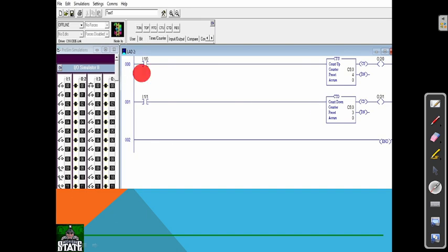If it is a sensor or an on/off switch, if I press this button over here 4 times, because here I denoted a count of 4, turning it on and off 4 times, then only will this output turn on. The thing is, we have to count for some certain process. That is called an up counter.